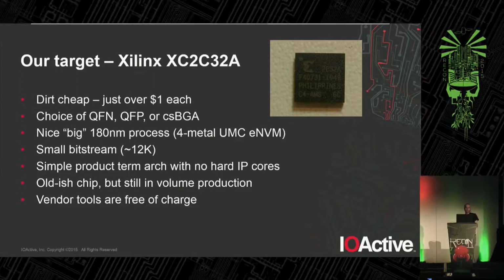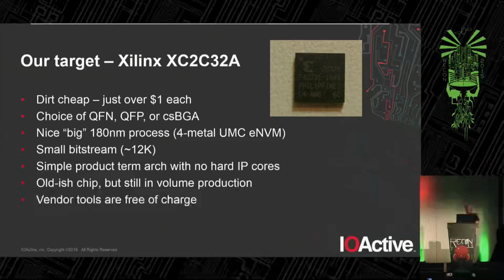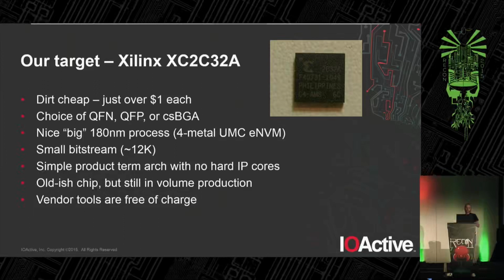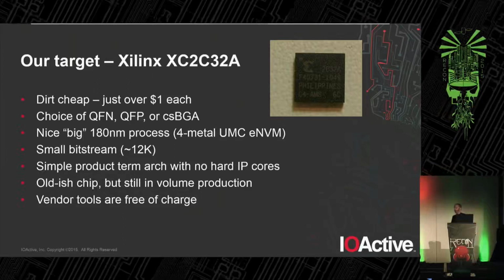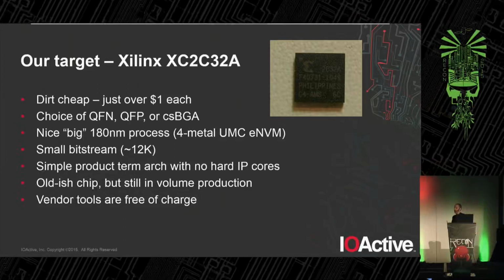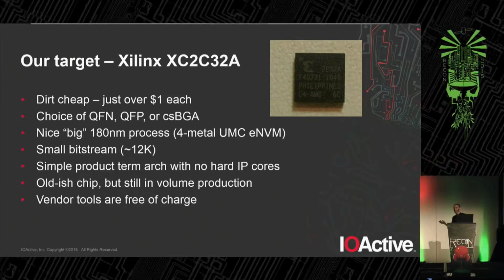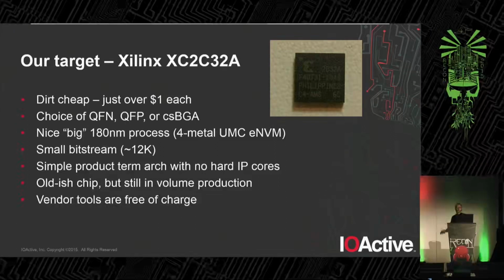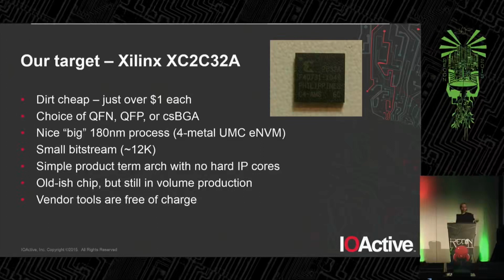The bit stream is also not that big. It's around 12K, so there's not really that much there to reverse. And it's also a fairly simple architecture. You're not going to find block RAMs and embedded ARM cores and all kinds of stuff like that. It's just pure programmable logic. And the vendor tools are free, which always helps.